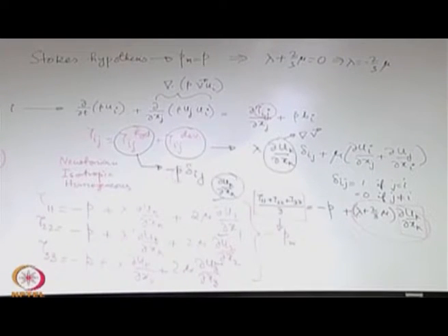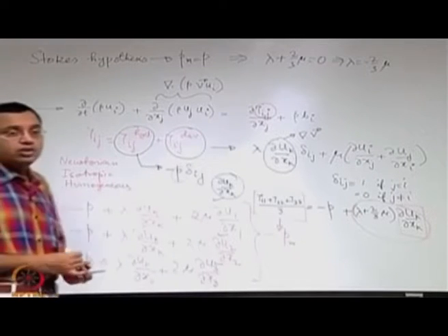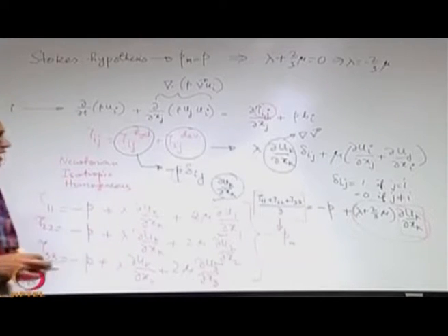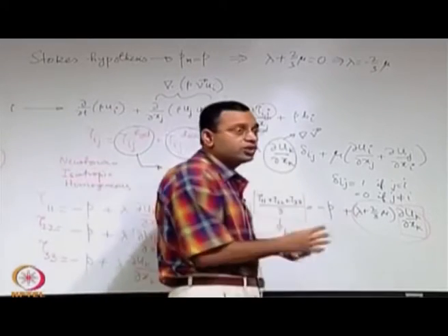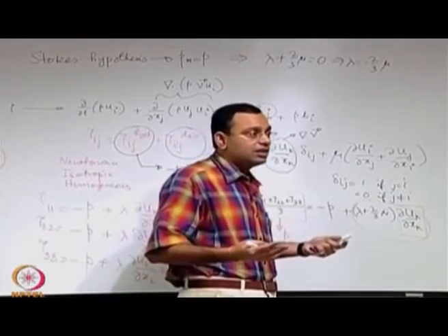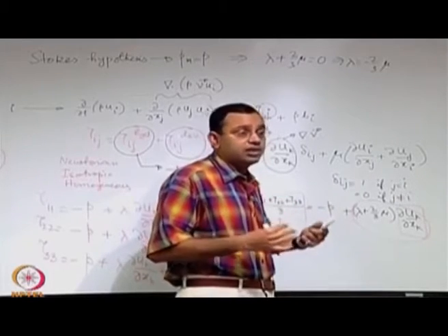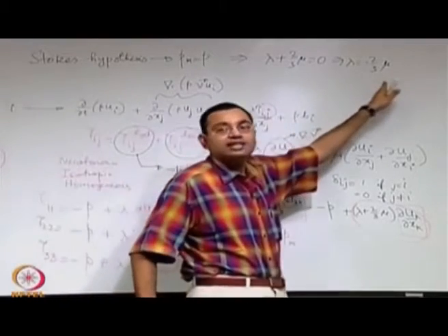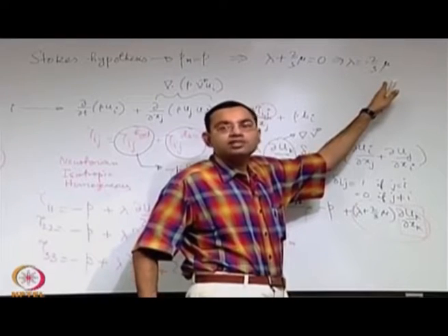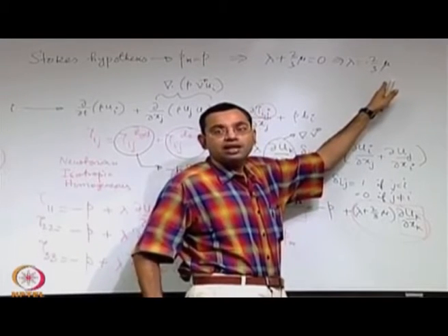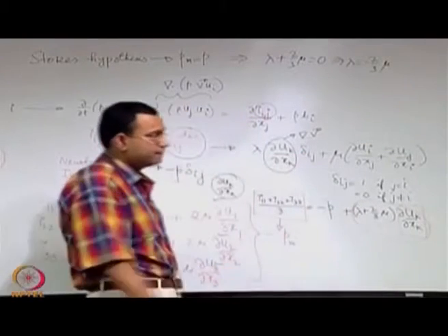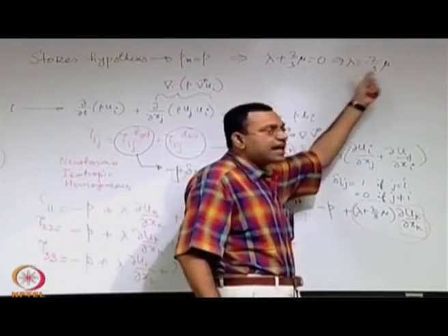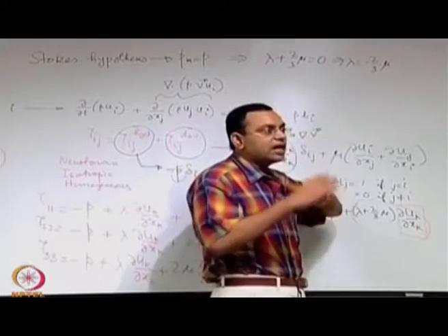There are certain fluids for which we do not care whether this is obeyed or not. What are those special fluids? One we discussed is monoatomic gas. So, if you have a monoatomic gas, it has to be obeyed, not that we do not care whether it is obeyed or not, it is not a hypothesis anymore, it is an exact reality. So, for a monoatomic gas this exactly will be valid, and therefore, no question of approximating mechanical pressure with thermodynamic pressure, they are exactly equal for a dilute monoatomic gas. But for other gases this is not an exact relationship, but this works because of the time scales that we talked about.